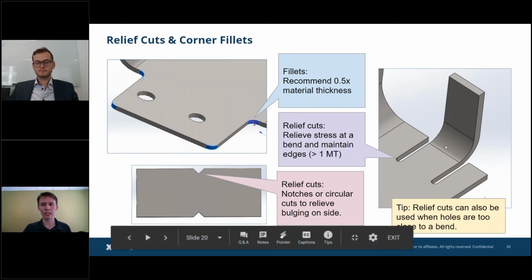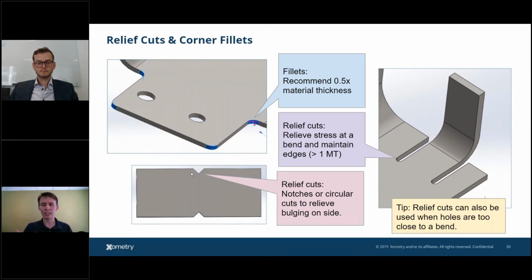Extremely useful to add to any project that you're working on. Although, in this drawing, the relief cut notches I usually will make round, having cuts along the bend also prevents that edge from flaring out when you're bending the material. If you imagine curling up a box, you'll see some flaring out right on the edge. Simply design in some snips there. That flare will still exist to a degree, but at least it won't be interfering with the outer dimensions of the project.